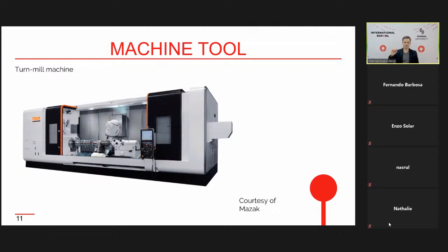That's why, for some parts, when we need only turning machining, they will be too expensive if we make them using this type of machine. It would be cheaper to make a part with rotational surfaces using only a turning machine, because a simple turning machine itself is cheaper. That's why machining using it also will be cheaper. That's why the number of these machines in manufacturing plants is usually not very high. So manufacturers also use separate turning, drilling, milling, grinding, and other machines.